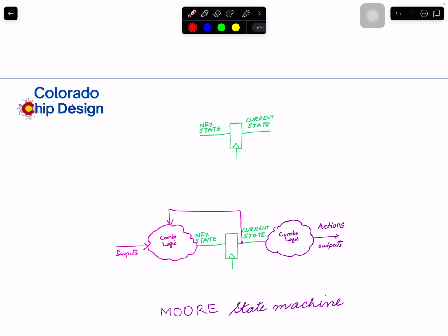On every clock edge, whatever next state we calculate, whether staying in the same state or changing it, D goes to Q. So our next state becomes the current state. Then the next state is calculated again, in the digital circuit context.